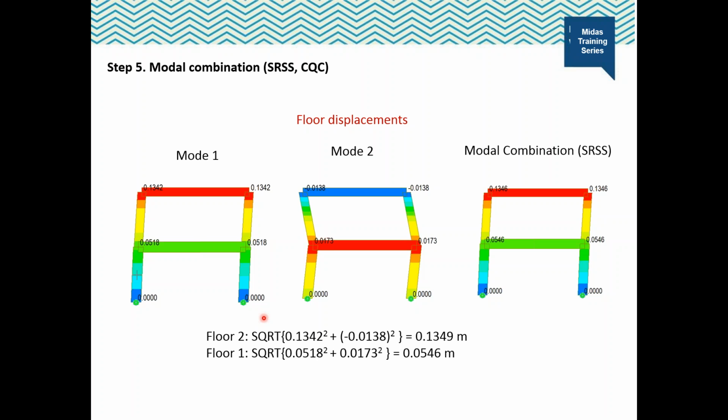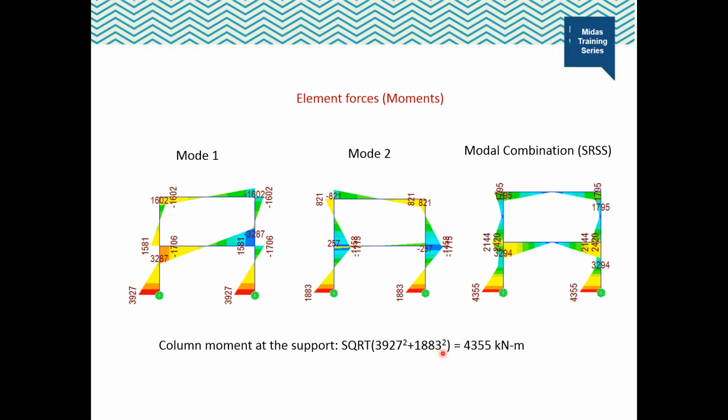This is the modal combination for the floor displacements according to the SRSS rule. This is for the element forces. As you see in the diagram for modal combination, the moments are always positive because of SRSS rule.